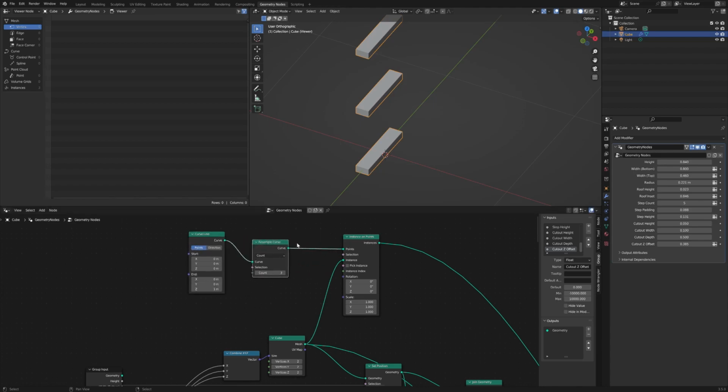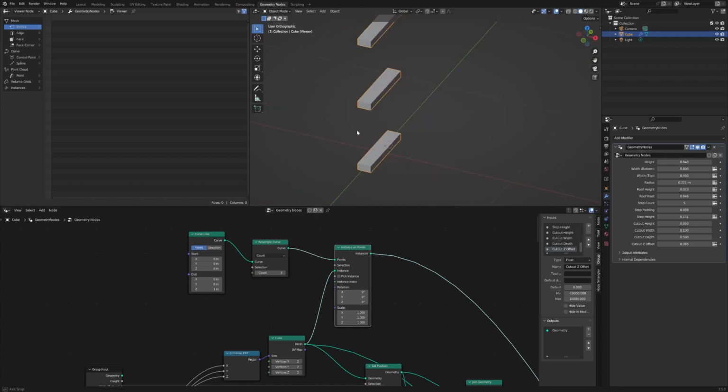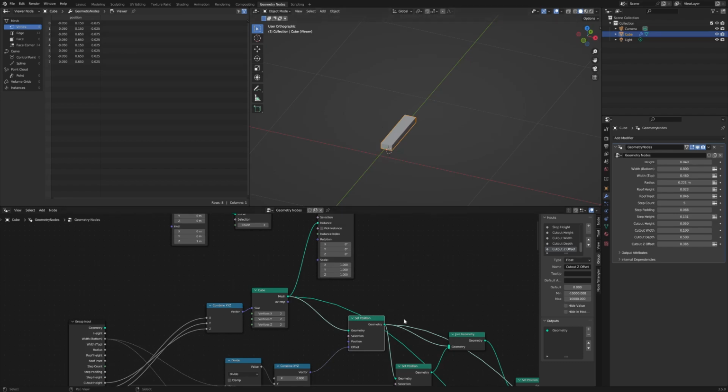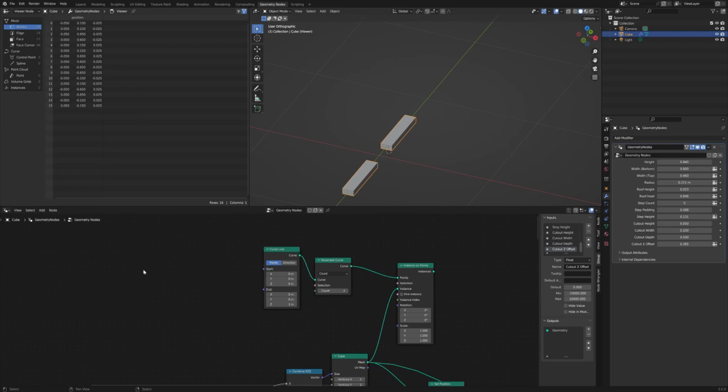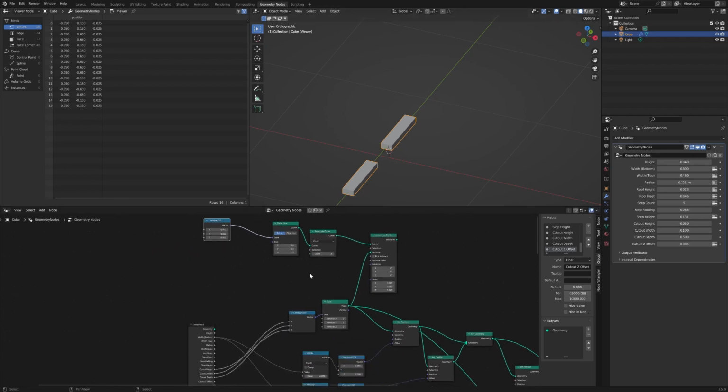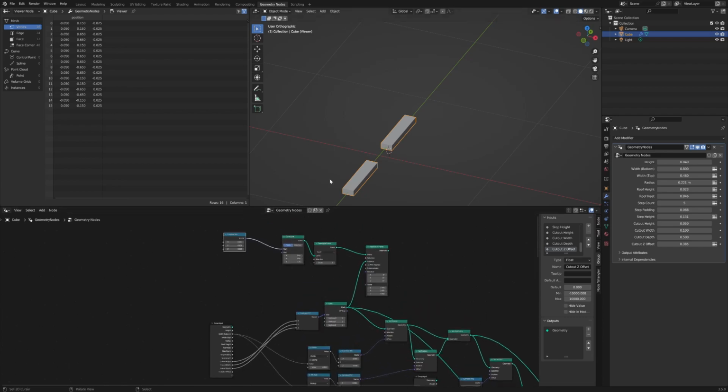So then what we need to do is make sure that this duplication, or the array as such, is in the direction that we want. And given that our cube is here, currently we're setting the position and then mirroring it in the x-axis to then join them together. We want to actually duplicate that array in the x-axis, and we'll offset it accordingly. So, in order to do that, we are going to add a combine x, y, z, and then we're going to define this x, y, z as the starting point, and the starting point is actually going to be defined by the width of our base object. So we want one point to be in the far corner, and then the end of the curve will be in the other corner.